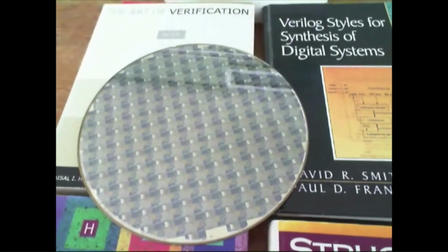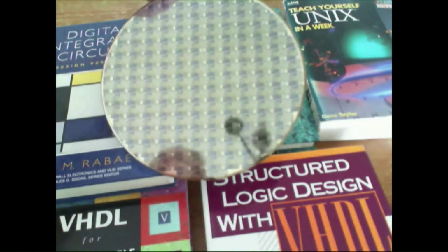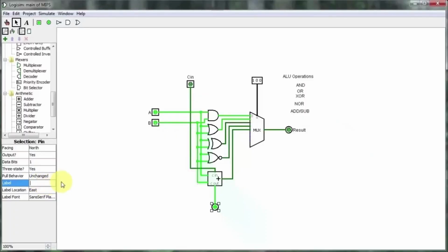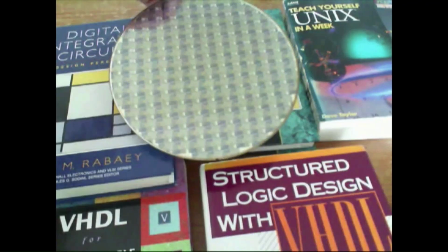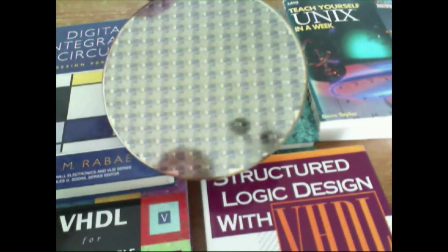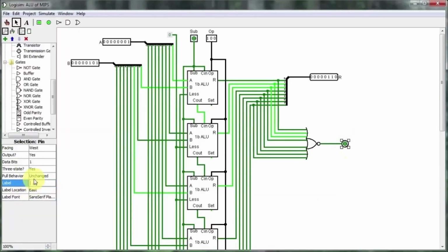Legality incorporates such constraints as the circuits not overlapping one another and remaining within the bounds of their placement area, being placed in valid orientations and in rows specified in the chip image, satisfying other restrictions supplied by either the user or the technology. Once the logic has stabilized, more emphasis is placed on achieving a high quality and legal placement. Some placement tools do ignore at least some aspects of legality during the optimization phase.